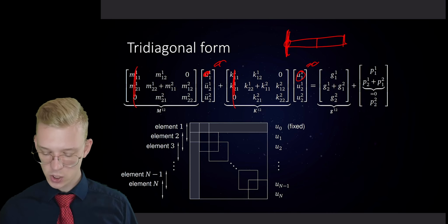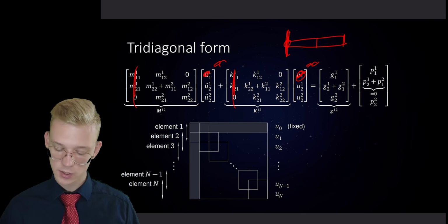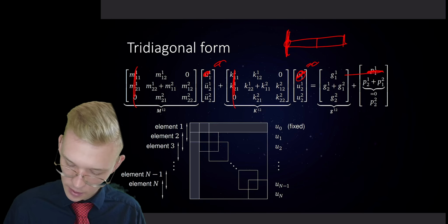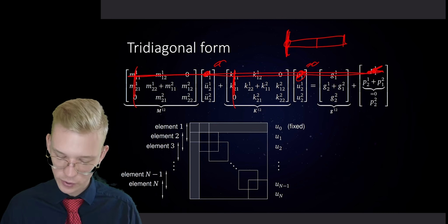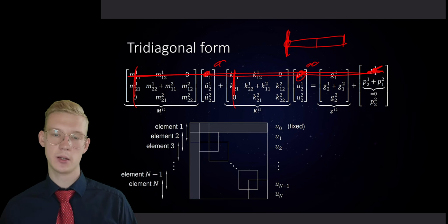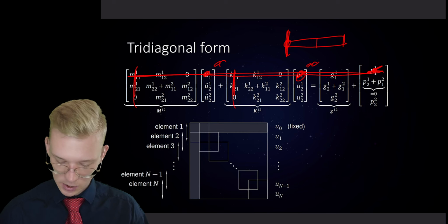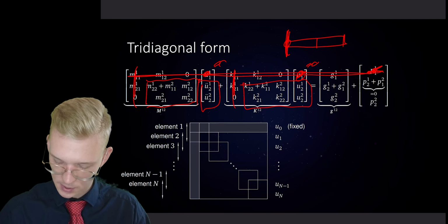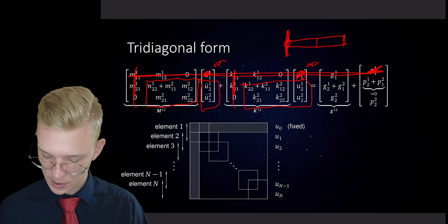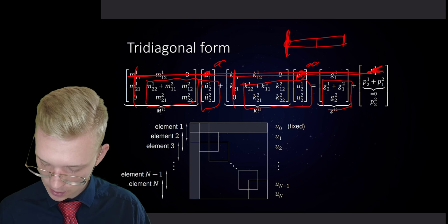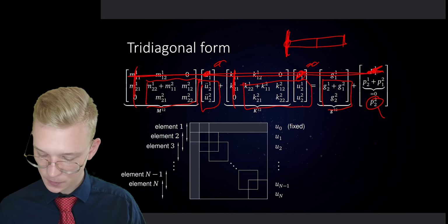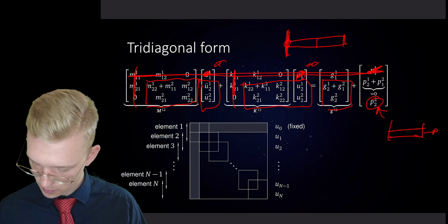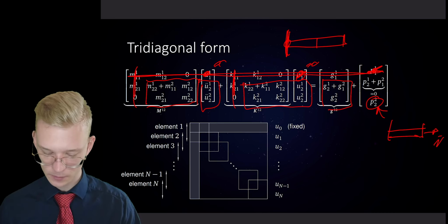But now the dimensions, if we remove that part, the dimensions don't fit anymore. So we will say that, well, for now, we just ignore the first equation. We ignore the first reaction force because we are more interested in the displacements for now than in the reaction forces. So this is how we are left with a 2x2 system with the stiffness and mass matrix and our forces and one reaction force at the end that we can, this is the force at the end of the bar. So this is N dash, better to say, because this is known.